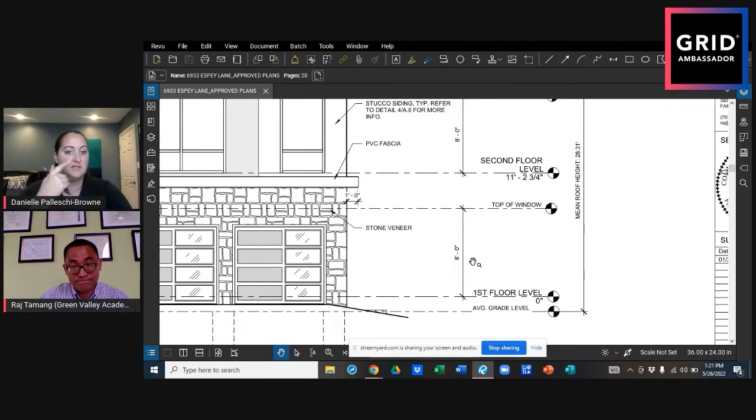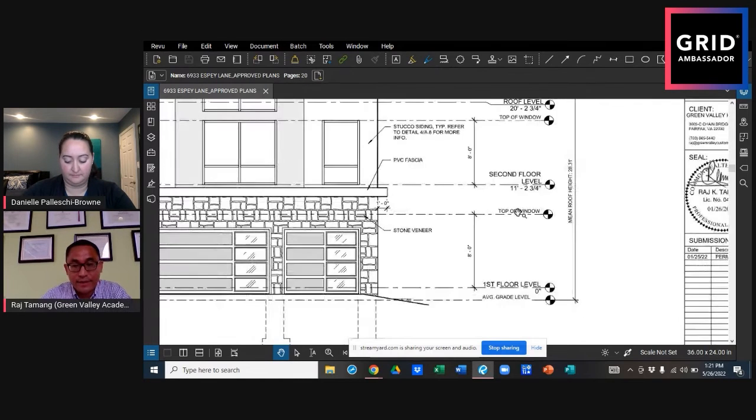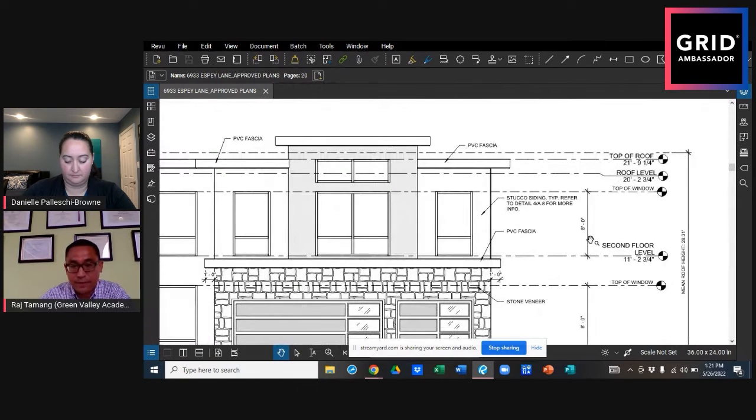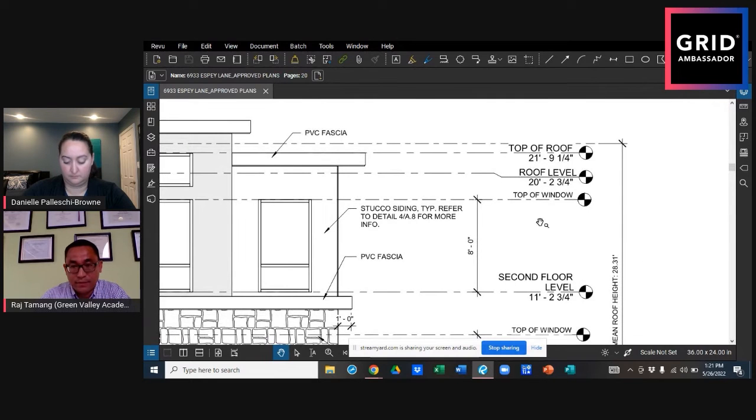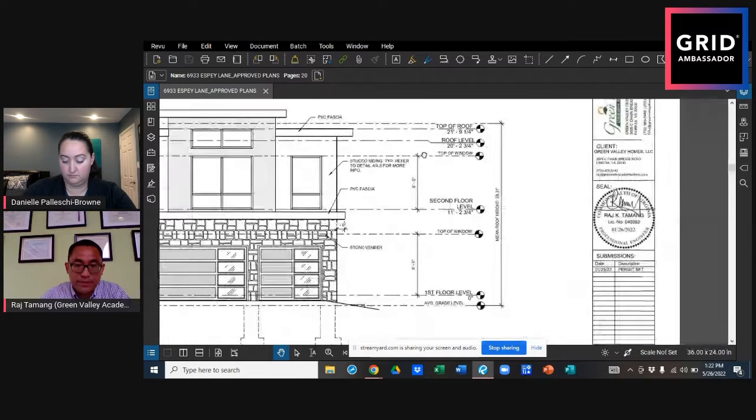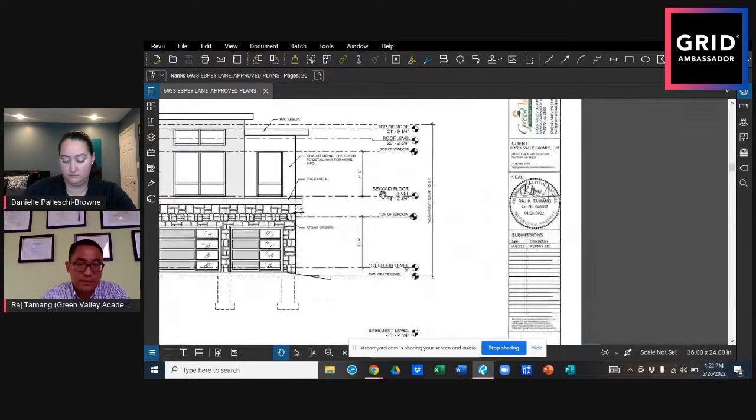So it's a whole space. Yeah, so it identifies everything in between those spaces, like in the ceiling and under the floor. Correct. That's including the thickness of the floor system, the joist and plywood, all that. From there on the second floor, 8 foot, and same thing here. So roof ceiling is 9 foot, so 11 2 3/4. So roof height, all this information you have to show on the front elevation.